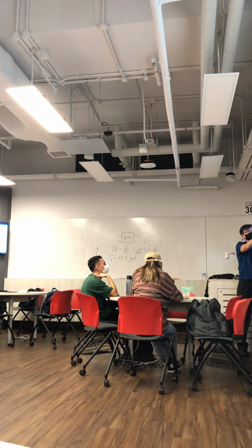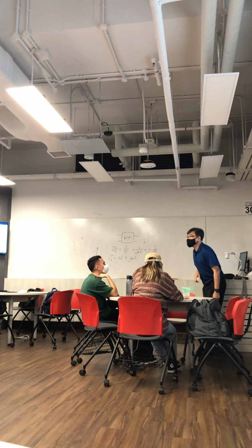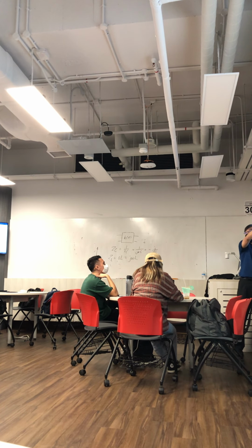So if I do the Laplace transform, I need to change the capacitor to 1 over sC. Then the voltage divider rule tells you this voltage is equal to 1 over sC, this impedance, over the total impedance R plus 1 over sC. Then you simplify and get 1 over (sRC plus 1). Substituting s equal to minus 1 over RC gives the pole.